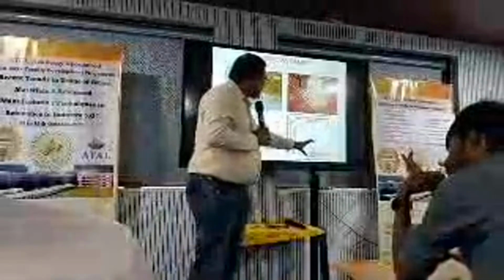And the third one is the tuned mass damper, where the damping mainly depends upon the mass and the stiffness. It mainly reduces the amplitude of tonal frequencies. You see the spectrum graph, at the natural frequency the amplitude is high. That tone amplitude, if you want to reduce, we have to apply the tuned mass damper. The amplitude at the resonance frequency we can reduce by using a tuned mass damper. This is the spectrum where the higher amplitude is there. This amplitude will convert to the lowest amplitude.